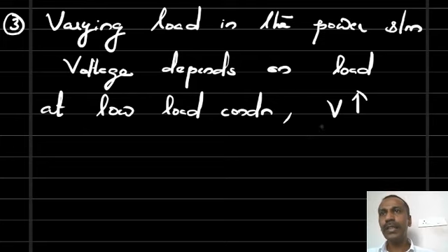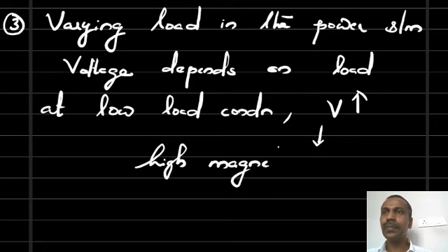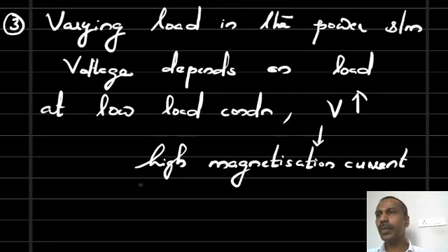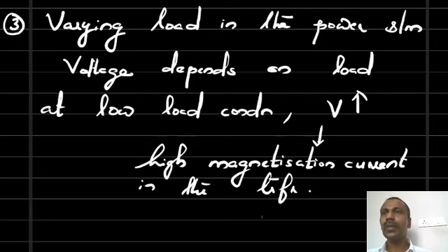When this voltage is high, it causes high magnetization current in the transformers. So these magnetization currents will also cause low power factor.